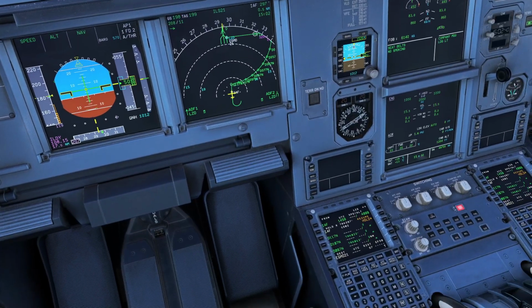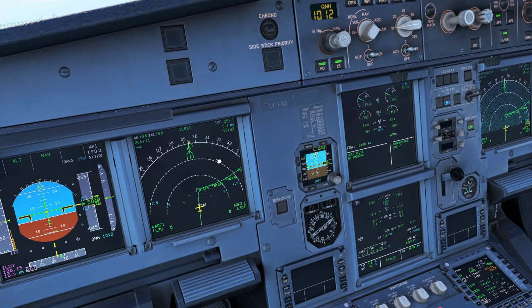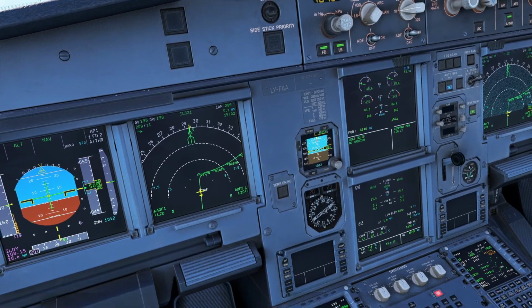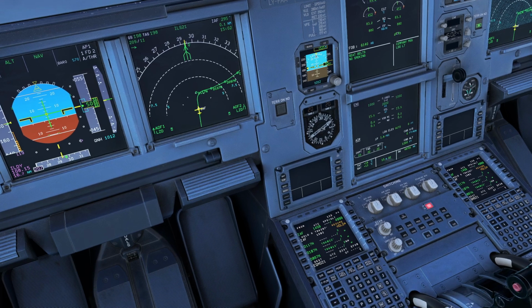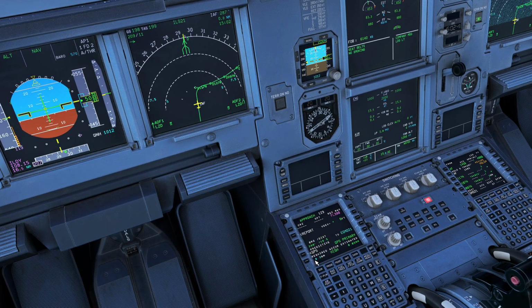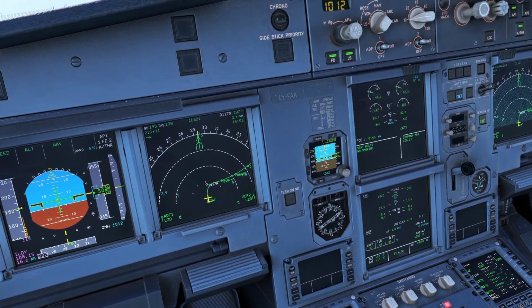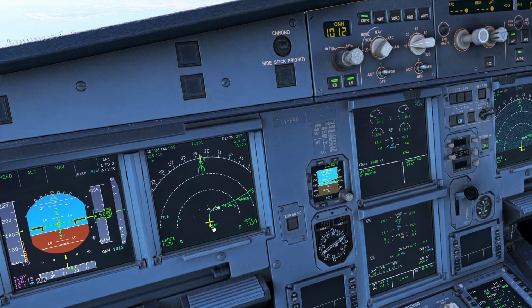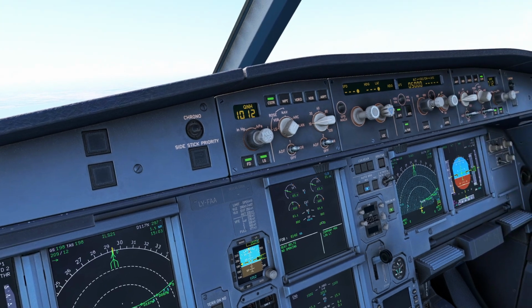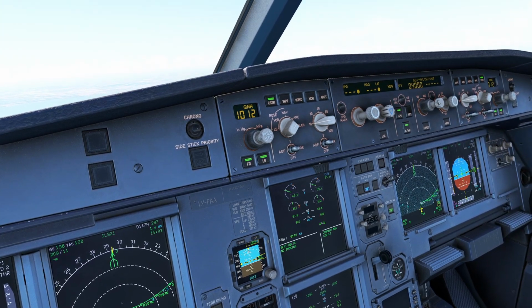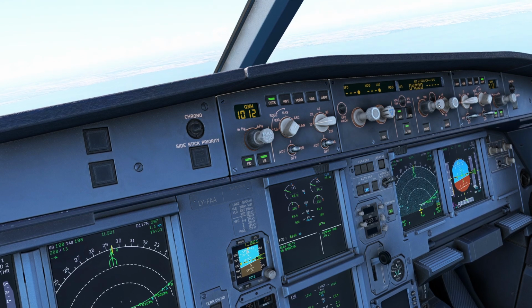Although I made this procedure manually in the MCDU, right now the GPS primary is available and accuracy is high, and I will also check the distance from the ILS as we proceed along the 14 mile arc. We can descend to 3,200.